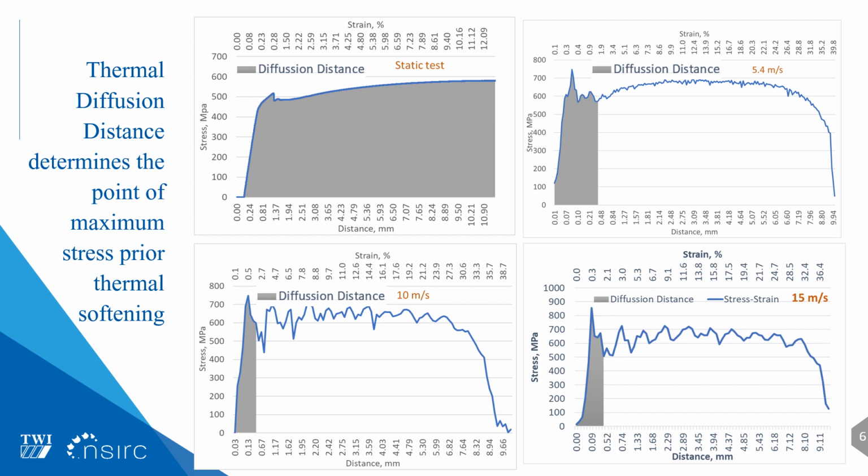But for the high strain rates, we see that the ultimate tensile strength is reached at the first part of the test, before thermal softening starts in the material due to the increase in temperature. This made us measure the ultimate tensile strength at the beginning of the experiment, after which there is a decrease in the stress applied, and then an increase in the ductility up to 3 times that of the strain rate.